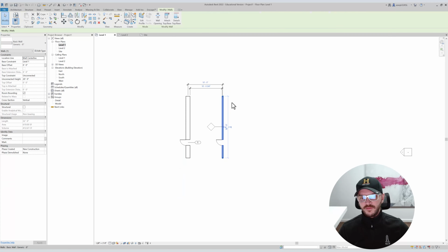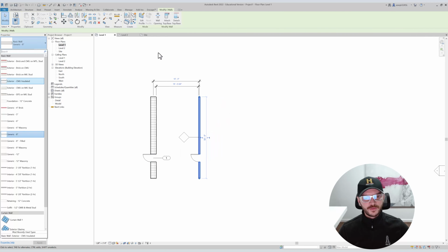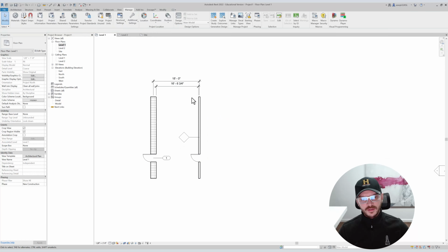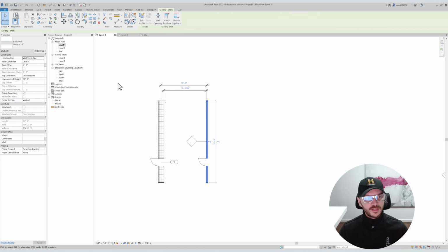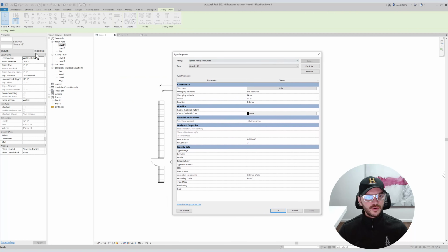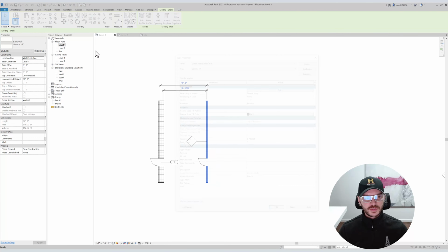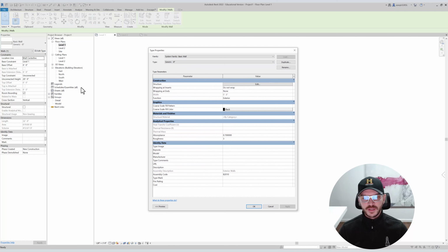And everything in between. So this is what the properties bar is for as well. And then what else can we do? All right, the 2-hour wall. So let's work on that filter. So when you want a new wall, let's say, you can go into edit type, right? You select the wall, go into edit type, and then here we are in this type properties, which is this,